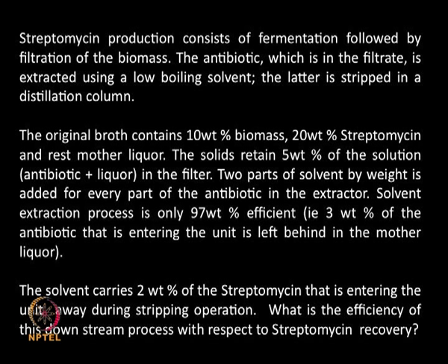The original broth contains 10 weight percent biomass, 20 weight percent streptomycin and the rest mother liquor, that is the liquid. We are interested in this particular product. Once you filter, the solids are going to be held in the filtration unit and the liquid passes through it, but the solids are not going to be totally dry. Obviously it will retain some solution, 5% of solution here. That solution contains both antibiotic and liquor. So some antibiotic is going to be lost in the solids.